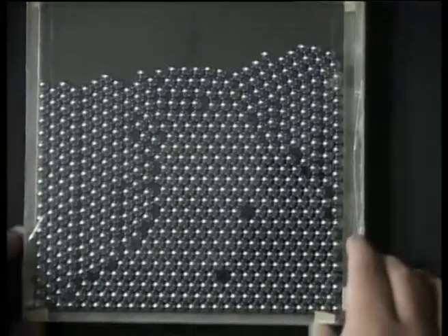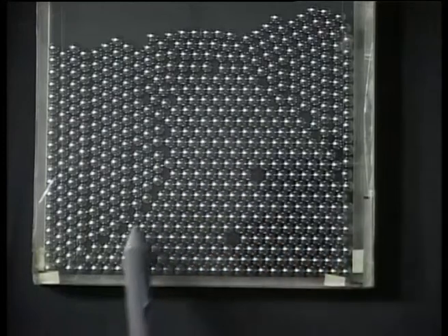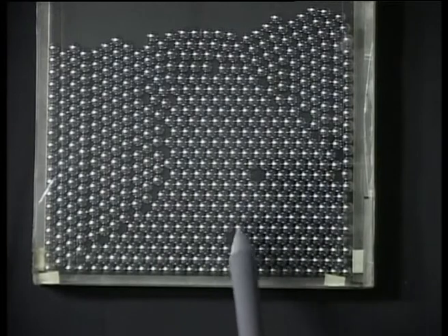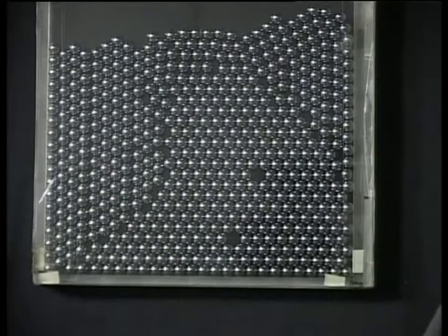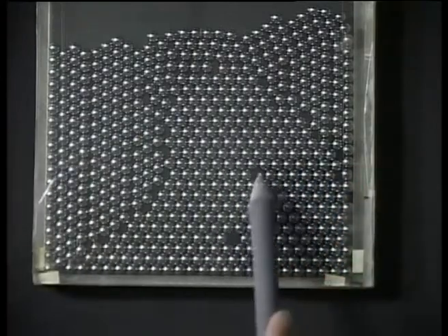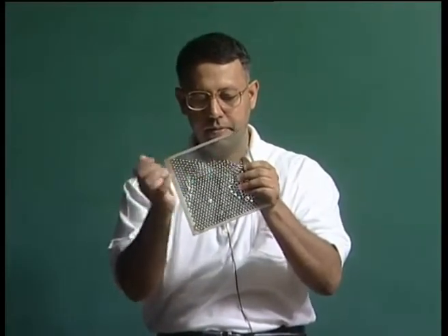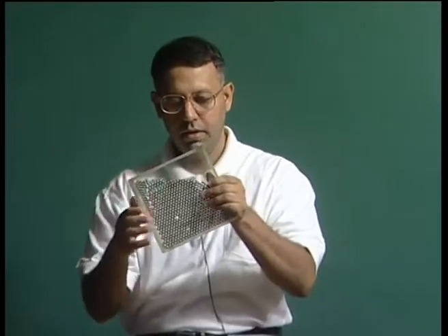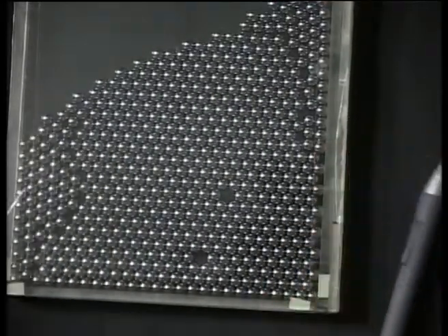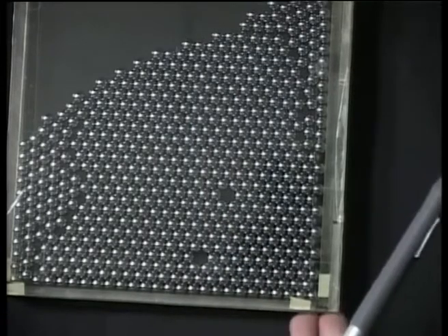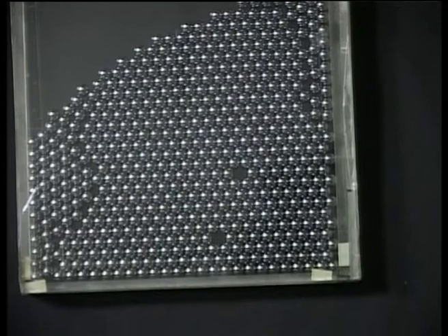So this is now my crystalline array of balls, and within this crystalline region, as you can see, there are 2 vacancies here. An important experiment we can do, keeping these vacancies in purview, is to take this model again and give some thermal vibrations to it. Then I put my model back, and lo and behold, in spite of all the vibrations I gave, you see these 2 vacancies are still there. So this is something we can visualize as the equilibrium thermodynamic presence of vacancies.